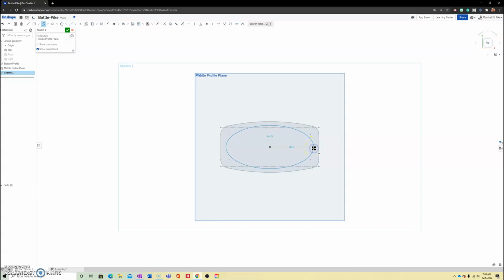And when I do my ellipse, I'm going to break it out, and it looks like in the drawing it's going to end up somewhere around there, but I will have a major and a minor axis that I will left click to activate, and it lets me know that it's vertical. You're going to want its point to be coincident inside, and that's where I will be when I drop it in. So turn on your constraints, and you can see here that I have it coincident, and it is actually on the horizontal. So let's go ahead and turn it off.